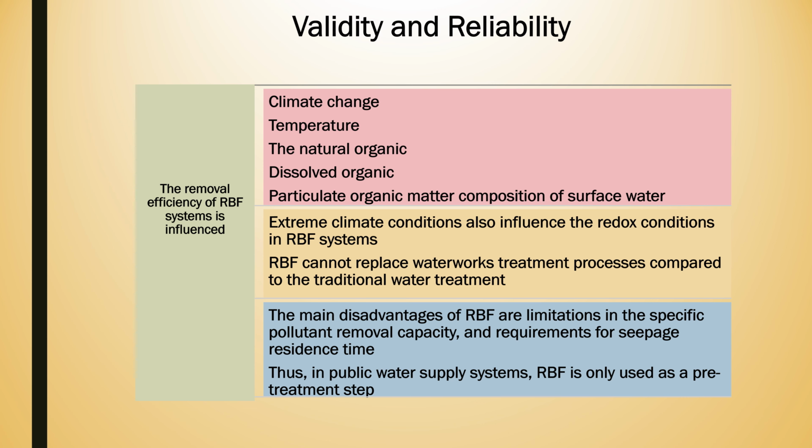Okay, RBF cannot replace waterworks treatment processes compared to the traditional water treatment. So the main disadvantage of RBF is the limitation in specific pollutant removal capacity and the requirement for seepage residence time. Thus, in public water supply systems, RBF is only used as a pre-treatment step.